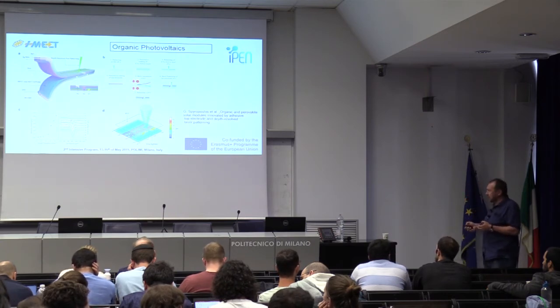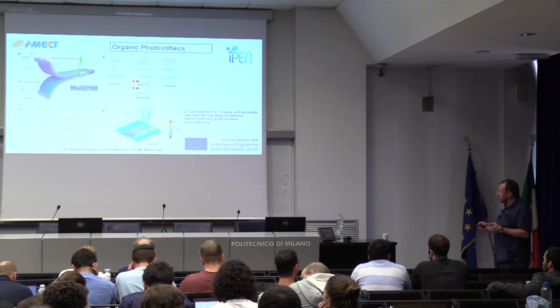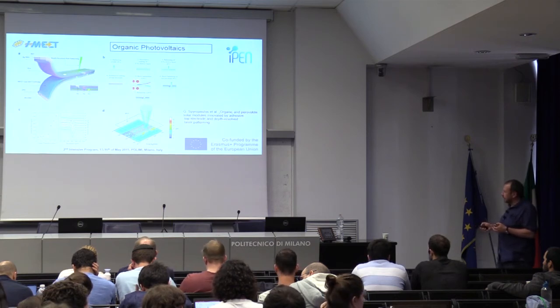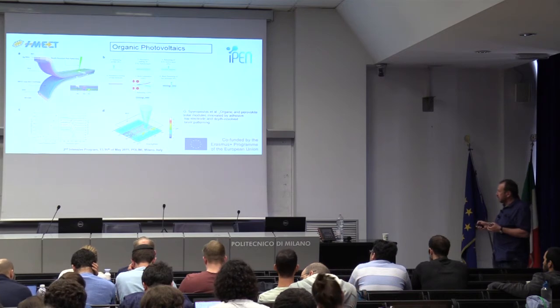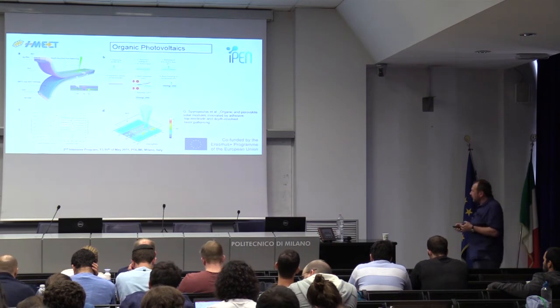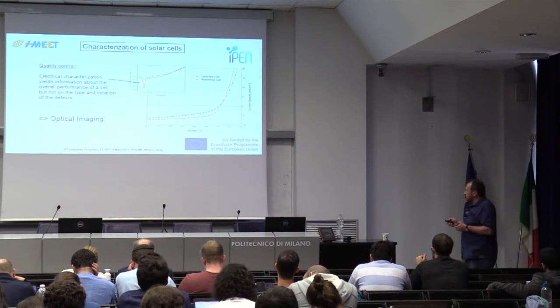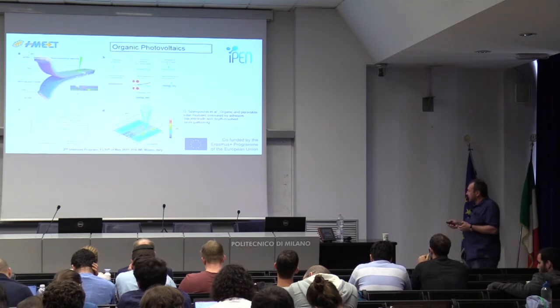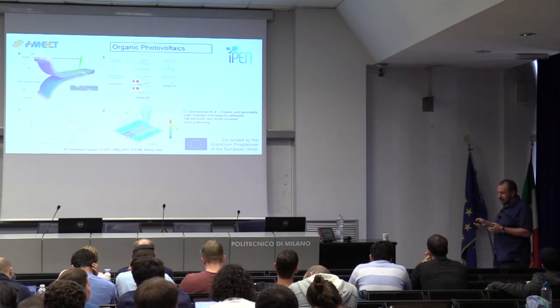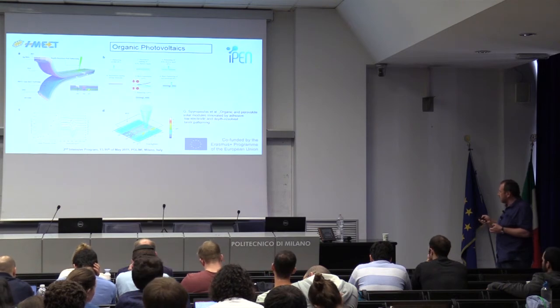This was done with a green laser which penetrates the PET foil. You can focus the laser slightly below this covering PET foil and just make a P3 groove into the top electrode. And this also worked very well. It worked well in organics and also in an example with a hybrid perovskite solar cell.